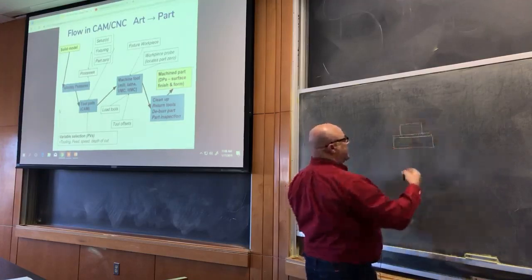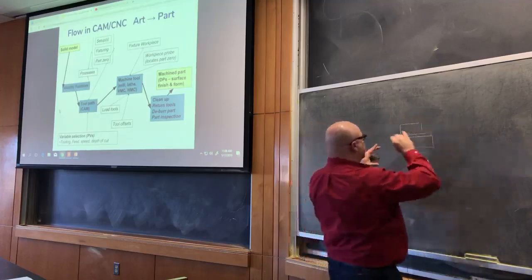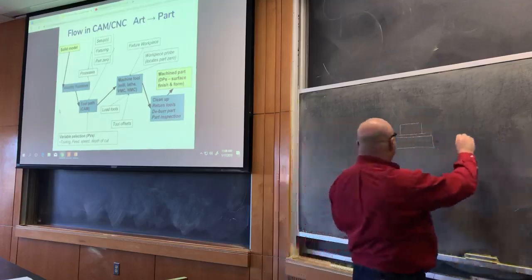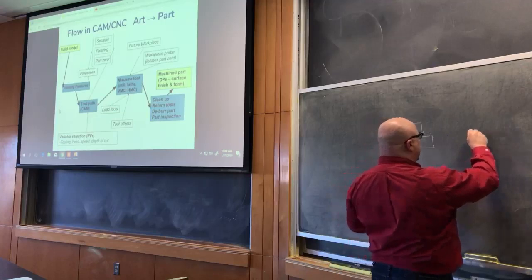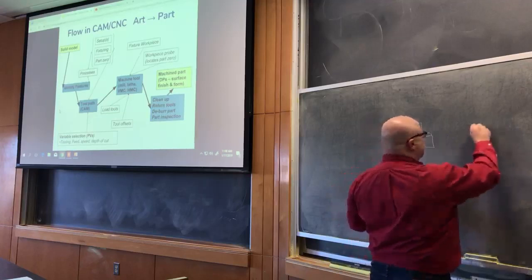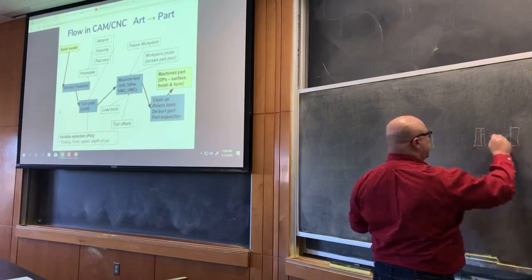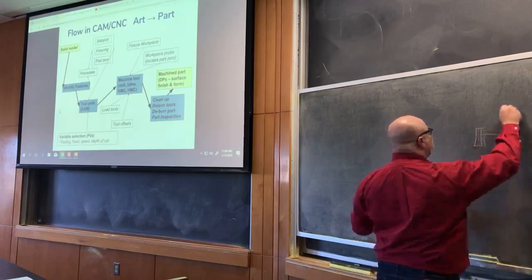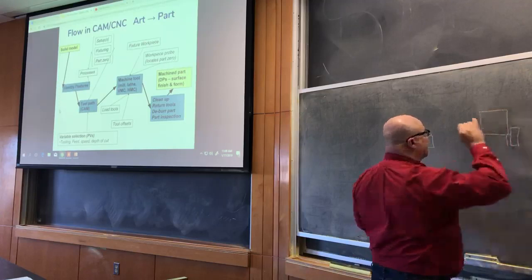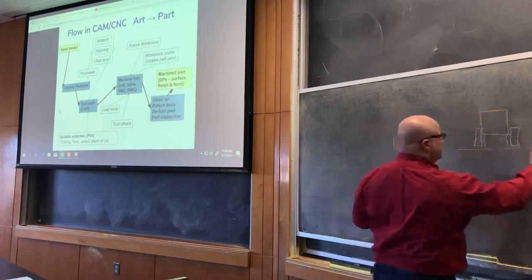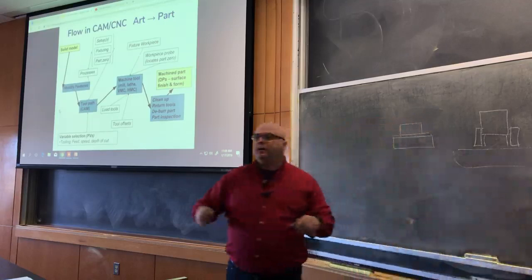Now there's another vise jaw in the back. So this is like the front view, like you're looking in through the door of the machine. The side view then would be vise jaw. We put these things called parallels in there, and we put the workpiece on the parallels. Looking from the side now, the vise body is down here somewhere.